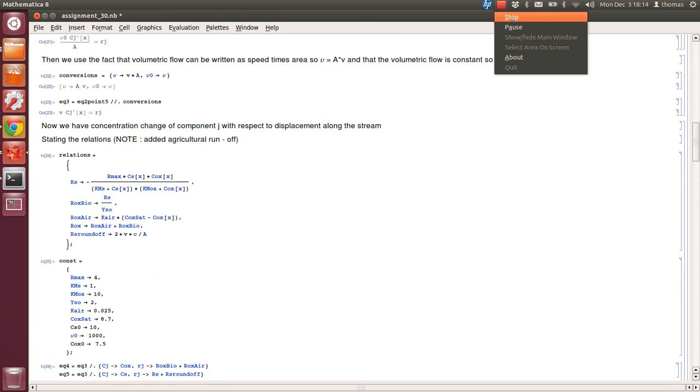So now I calculate the mix, and the mix will depend on whether we are adding or subtracting any kind of volumetric flow, and it will be multiplied by the concentration of that flow if it's something that's running into this system. If it's something that runs out, you will see that if I go up here, I will simply set the concentration to 0.